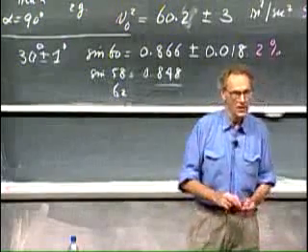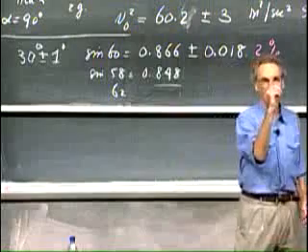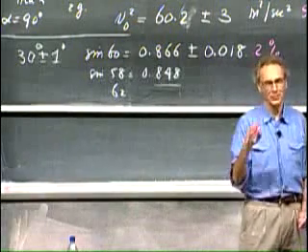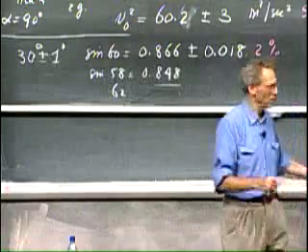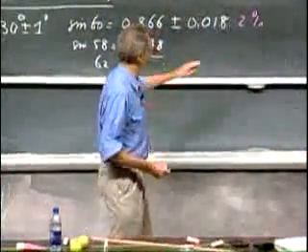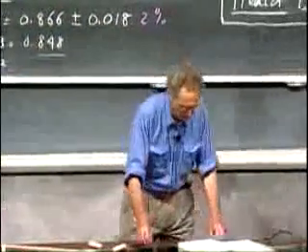And the reason is that a sine curve is like so. So a small angle change here makes no difference. But a small angle change here makes a lot of difference. And you can see that it is the slope of the sine curve that gives you a much larger error if you are off by a teeny-weeny little bit.